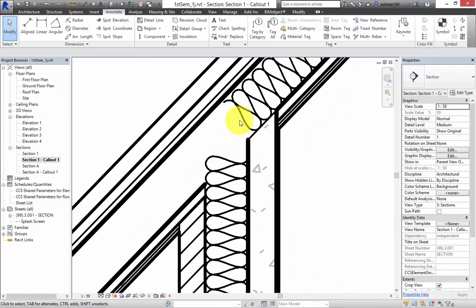And what usually happens is that insulation is extremely important, as Alan has probably told you, but it's also important how you represent it on the screen here, because people read these drawings. People are used to reading drawings. They really take a lot of information from these drawings. So if I left that like that, it would probably be built like that, and it would be built with an enormous cold bridge between the inside and the outside.